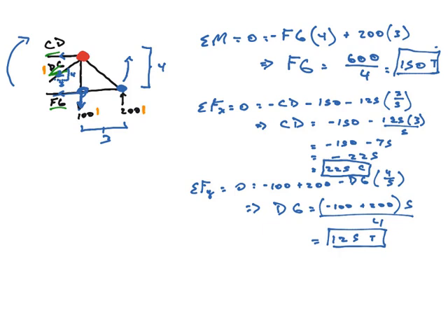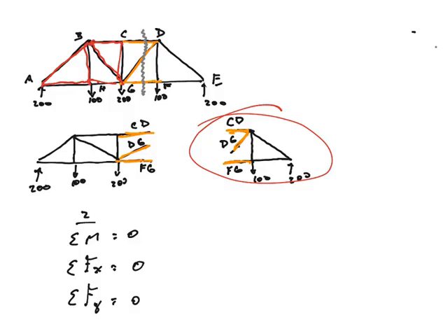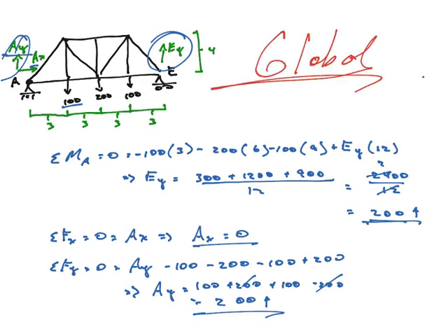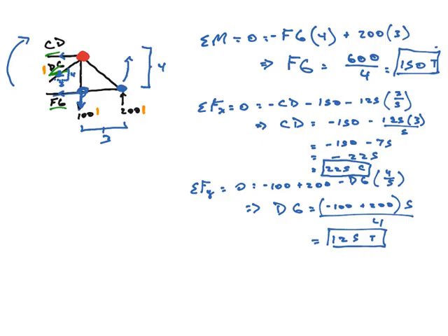And the other good thing about it is all you're doing is the very first step of all truss analysis we always do every time, which is global equilibrium. We're just doing it again a second time to find out these three external forces because we've broken these members. So now those members are not nice internal forces. They're like external loads now. And we're trying to calculate those external loads. It's like trying to find the reactions all over again.